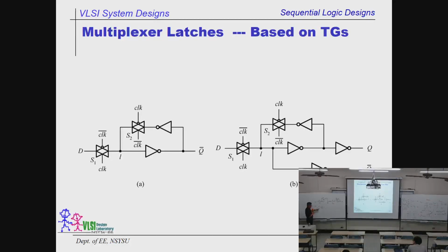Right now, let's change the clock to low. Change to low, this one is disconnected. This one is on. It's looping. And the new data, because this one becomes 0, the inverse is high, right? So the data we just copied will be copied again to over here. And this one is disconnected. So if we copy the two to design, but driven by out-of-phase clock, we are going to have exactly the same function just like the one over there, master slave.